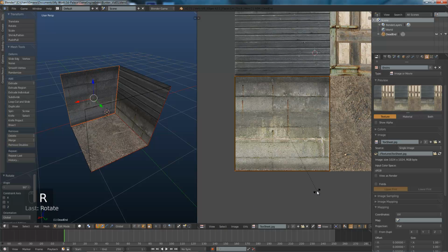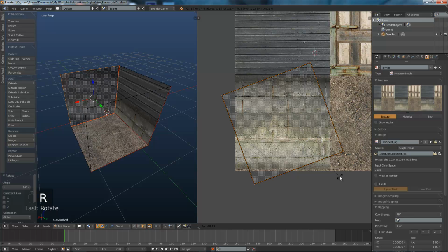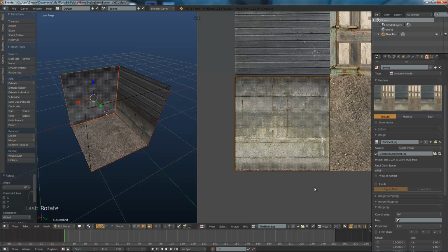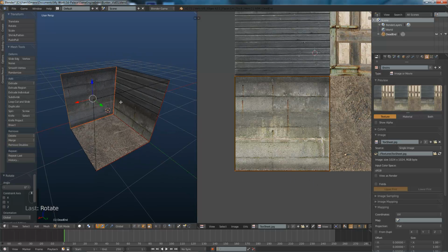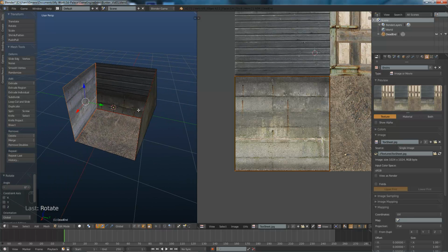If we hit R again, you can see down there, hopefully if you've got HD, it's going rotation -20, -10. So if we hold down Control, it'll go in 5-degree increments, and we can stop it where we want, which is there. Okay, so I just clicked to select that. So that's one wall done.